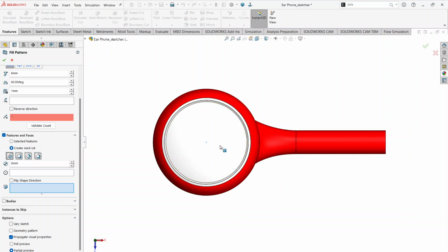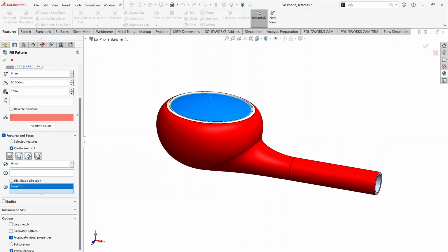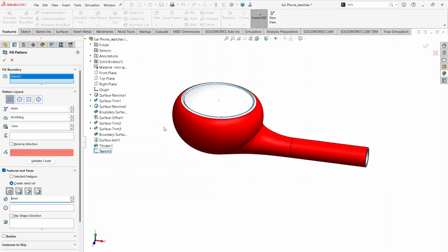Probably the face should be this face, we need to cut. Select the contour, set direction. Oh, you have to create a direction for each field. So what we need here is really a direction for that.